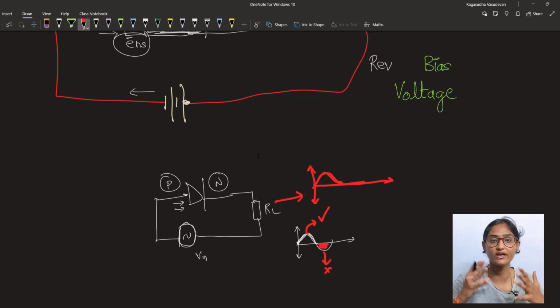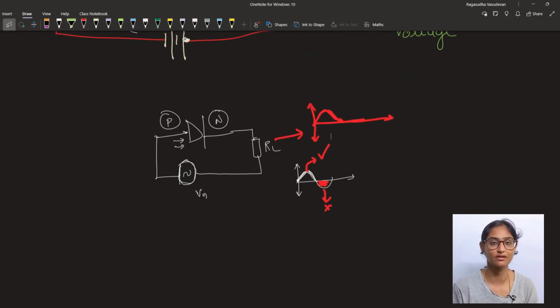We saw how a diode is formed from silicon. We have a P-type material, we have an N-type material. By combining both of them, we create a depletion region on its own, and by applying a positive voltage, this depletion region breaks down and you will have electron conduction happening from the P to N junction. Thereby the electron flows into the circuit and creates conduction, whereas in reverse bias, conduction doesn't happen.